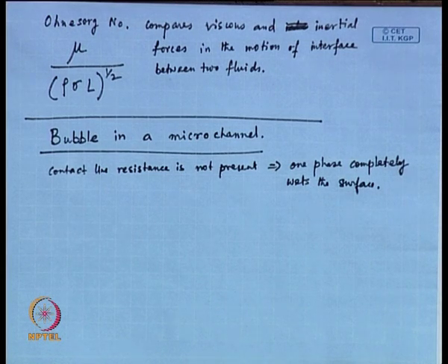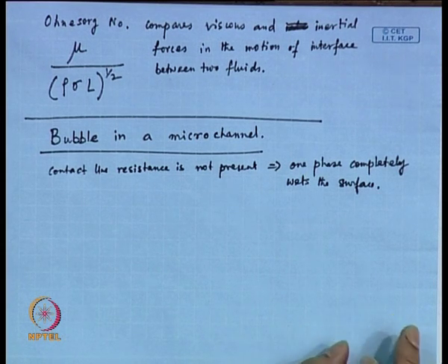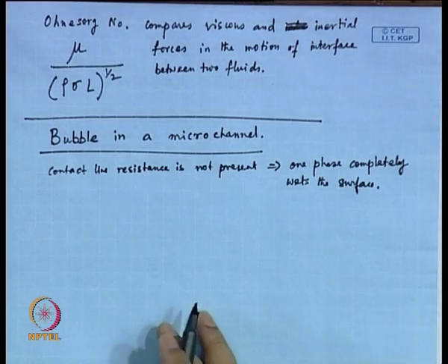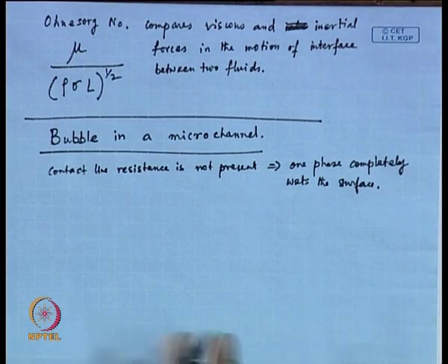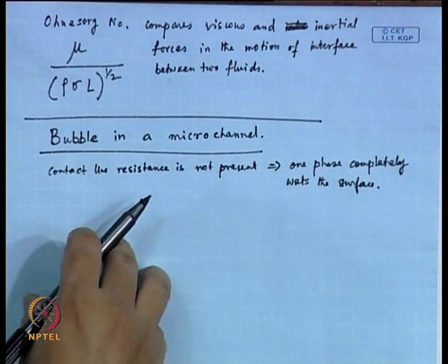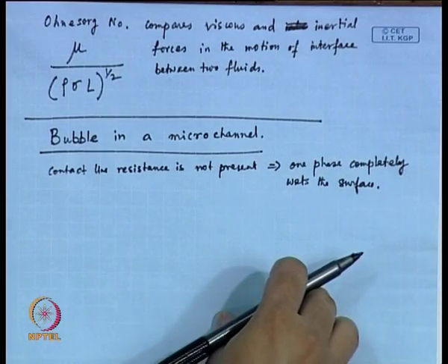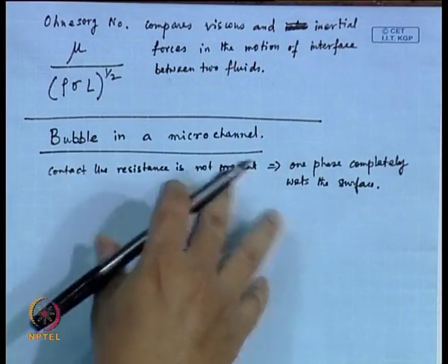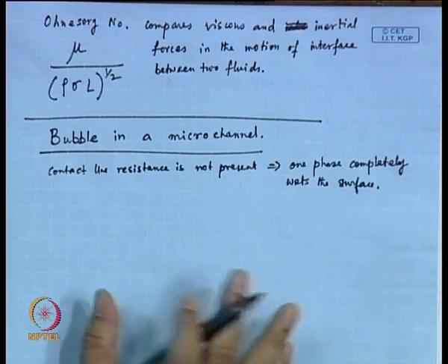The other point, I would like to play with the numbers to see what would be the importance of Laplace pressure and the pressure drop for a flow through a pipe. What was that, Hagen-Poiseuille's equation? If you take that pressure drop, and compare it with the Laplace pressure for the same channel, for similar dimensions, how do these numbers look? Let me point that out here.